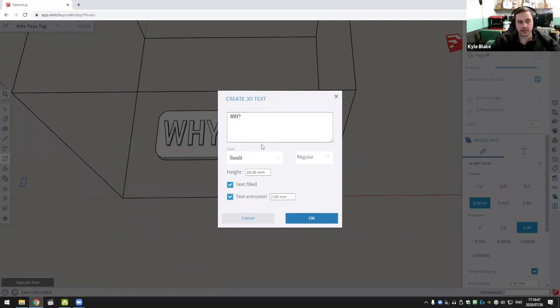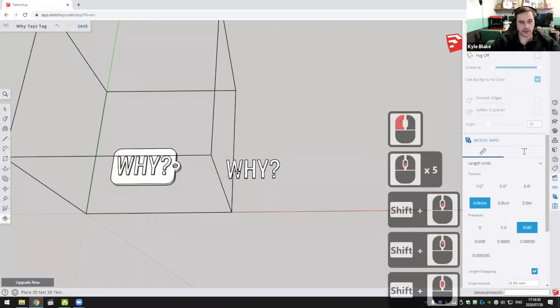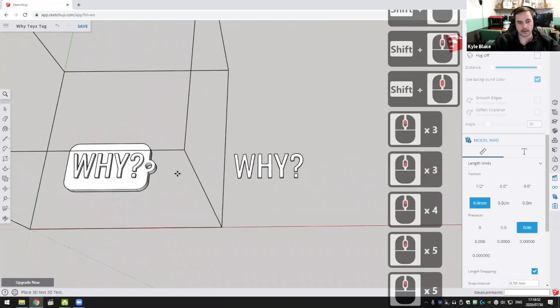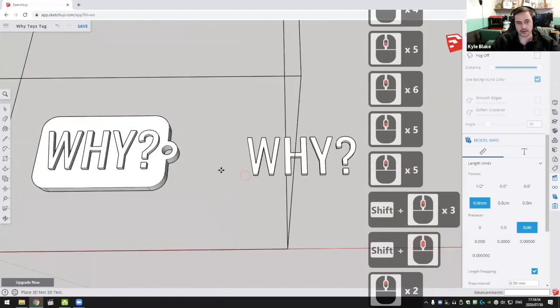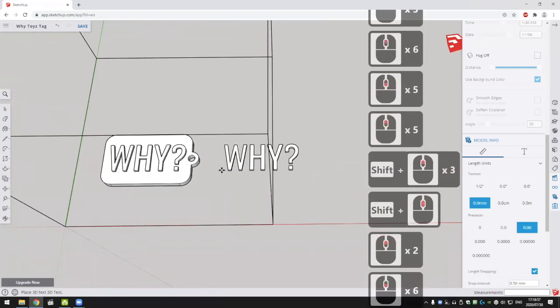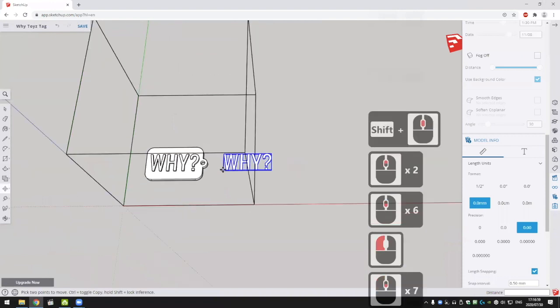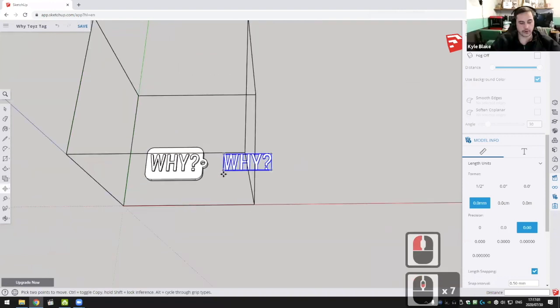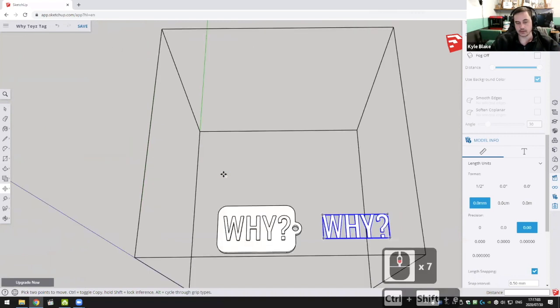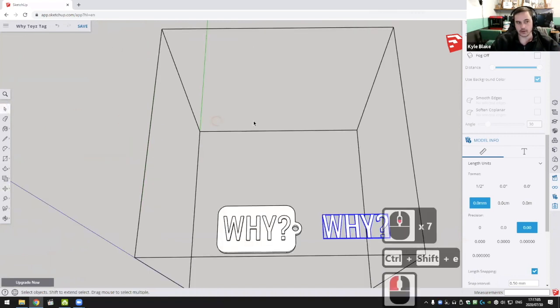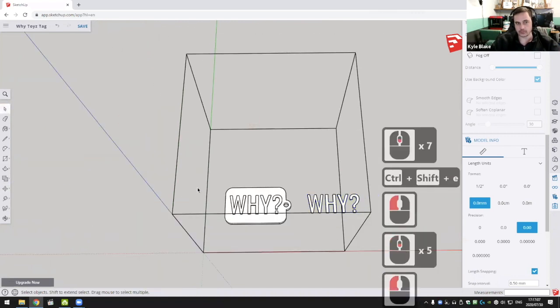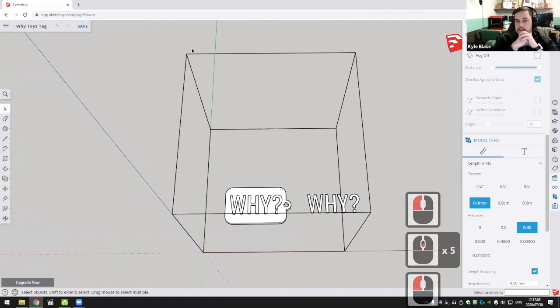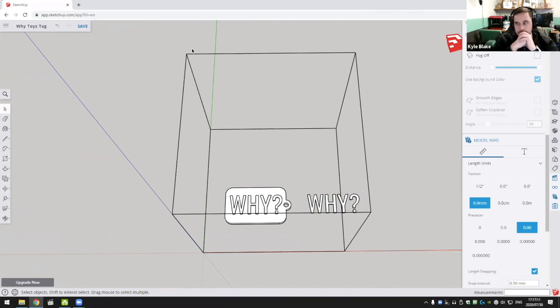So what you can do is, once you've typed everything and selected a font and pressed OK, you shouldn't see anything, but you do see the little black place cursor, right? Yes. So maybe just click, and then press Control-Shift-E, and everything in your workspace should be centered on the page. Do you possibly see text now? I'm going to try that.